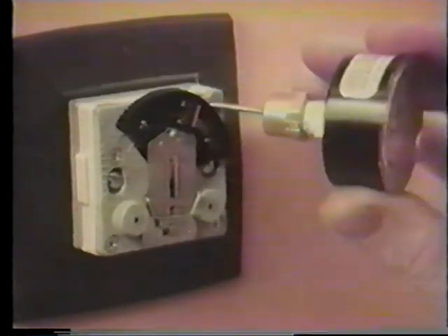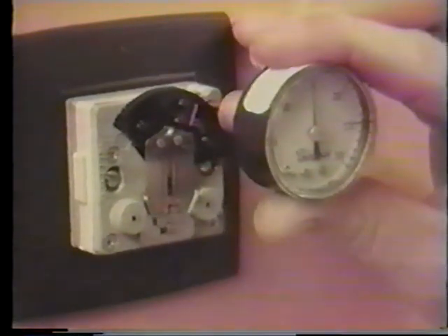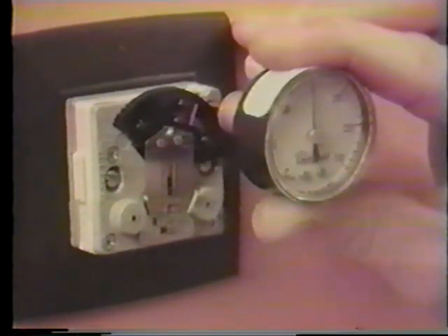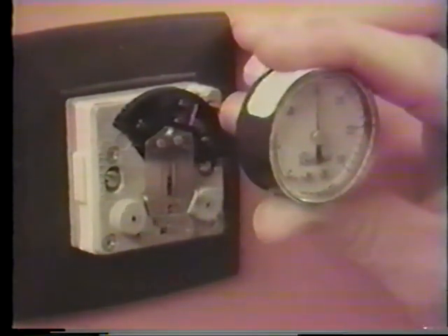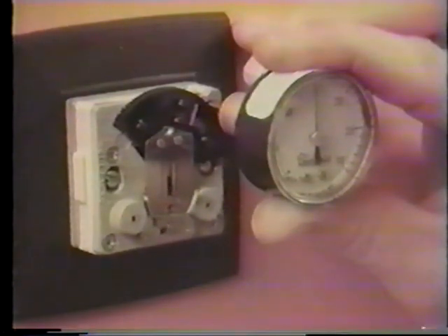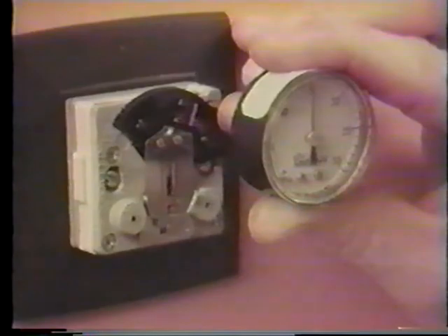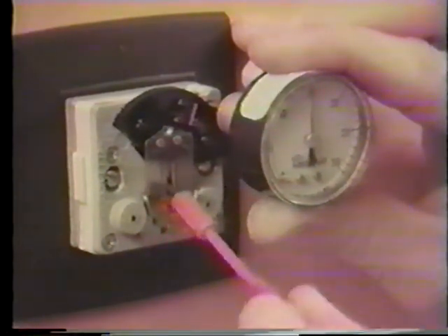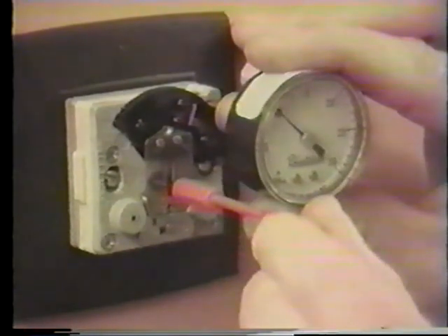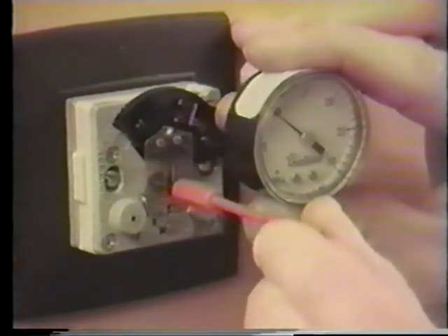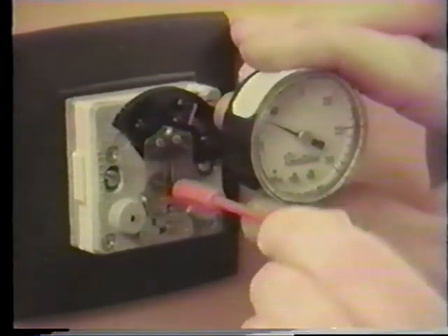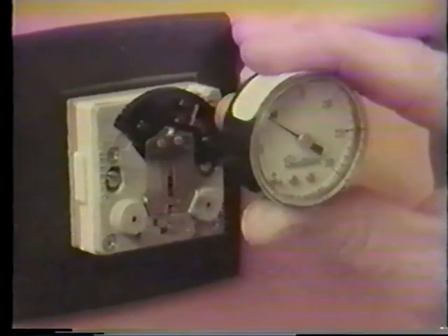Insert the gauge adapter so that the branch line output of the thermostat can be measured. Take care not to touch or breathe on the bimetal, or the sense temperature readings will be inaccurate. If the branch pressure is not 9 psig, use a 1/16 inch hex calibration wrench to turn the calibration screw until the branch line pressure indicates 9 psig. The thermostat is now calibrated.